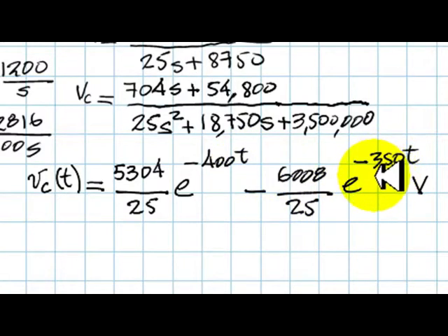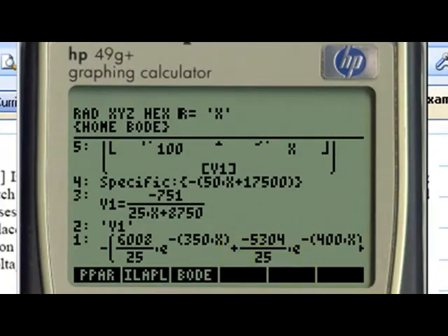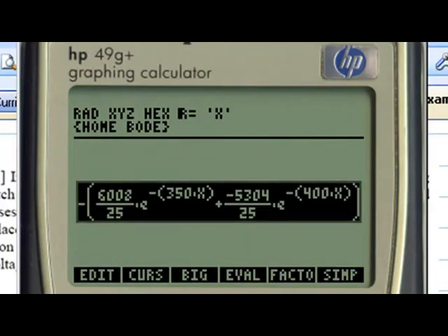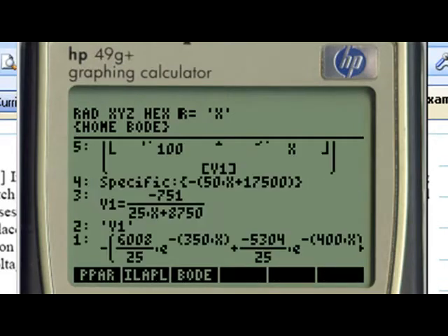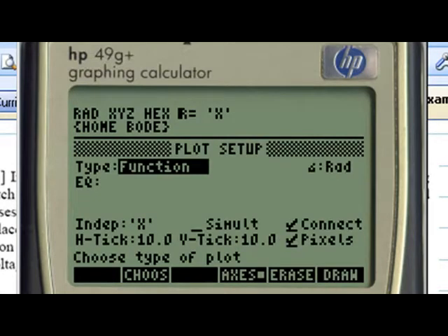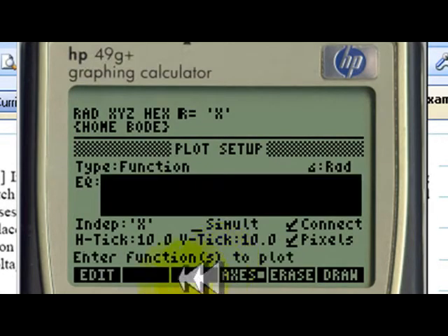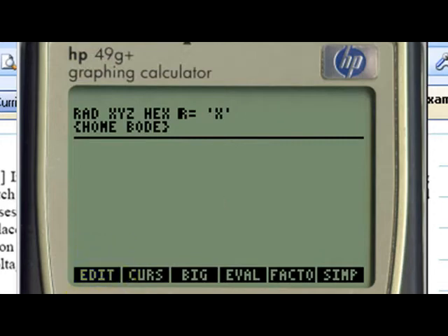We still need to plot this one as a function of time between t equals 0 and t equals half a millisecond. Let's do that. To do that, let me push the down arrow, and in there I go red, copy, enter, and I go here to the 2D, 3D menu. Push and hold the shift key, and in here go to equation, edit, and red and paste.